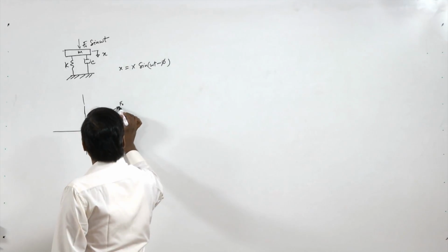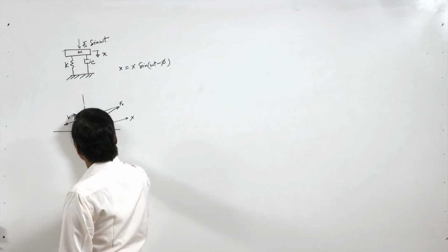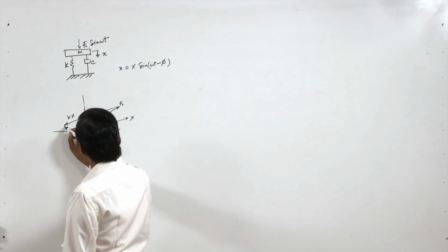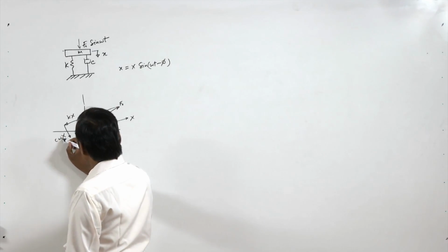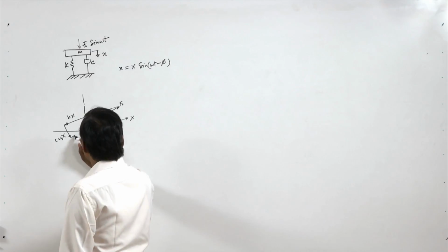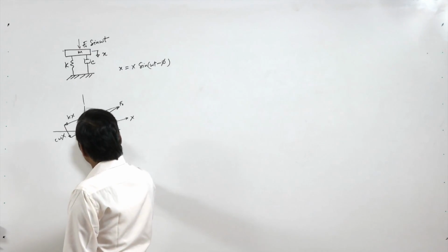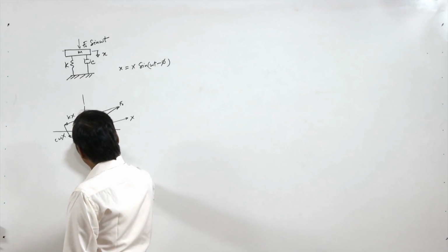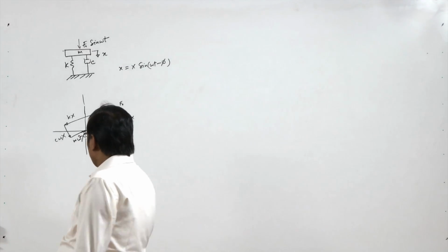Then there was the spring force kx, then the damper force at 90 degrees, c omega X, then the inertia force m omega square into X.